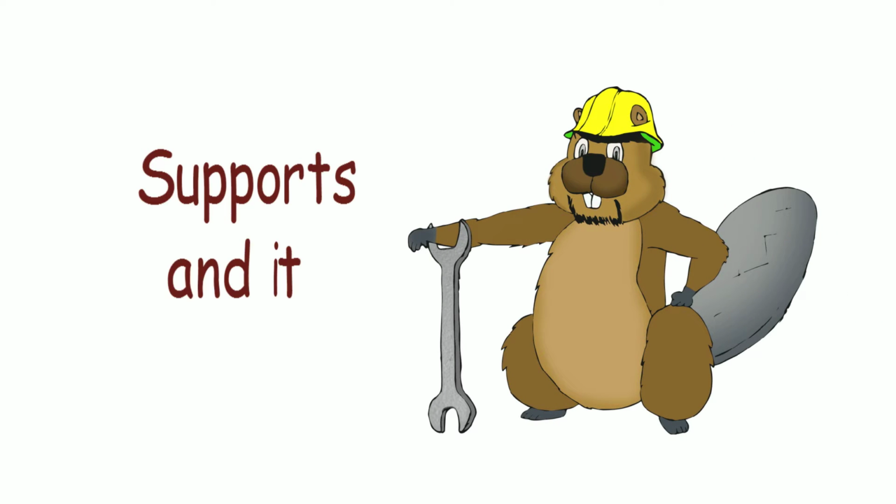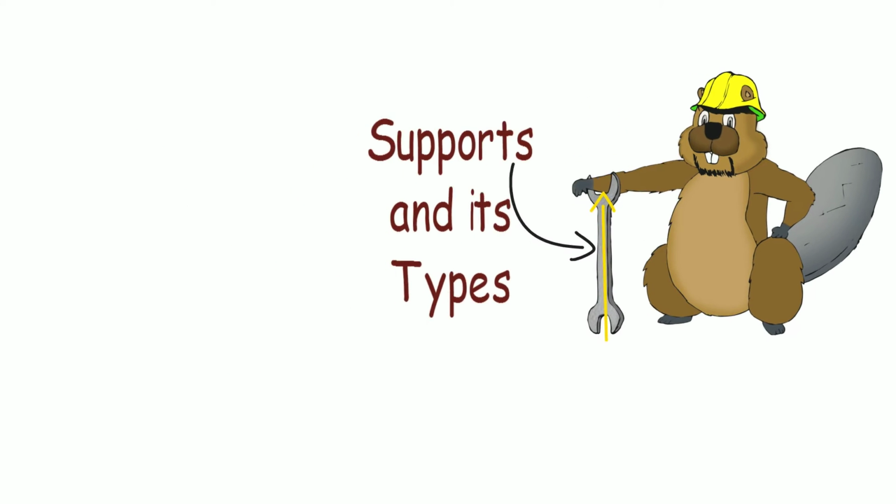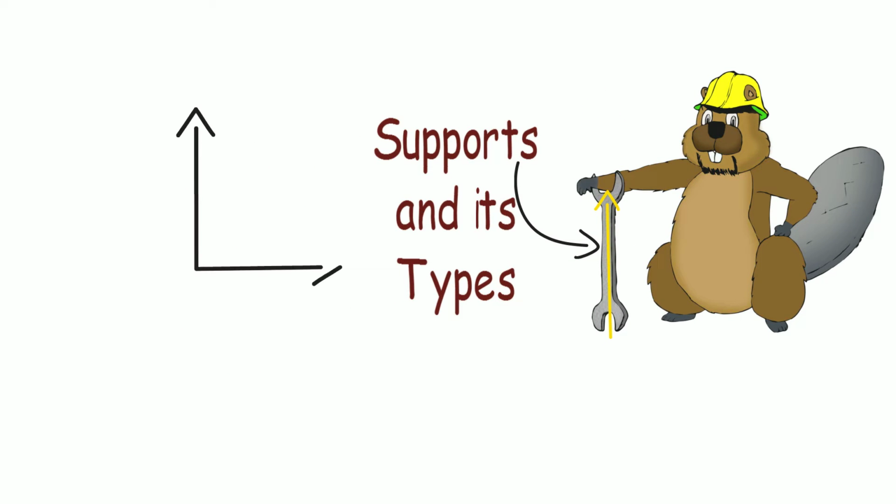Speaking about supports, the most important thing linked with it is the reaction forces the support exerts on the object it is connected with. Now, the simplest method to understand these forces and detect them is by finding its restriction to motion along the three axes x, y, and z axis, both translational and rotational. To ease things out, let us consider a planar condition, meaning motion along x and y axis only.